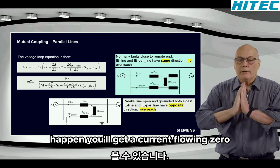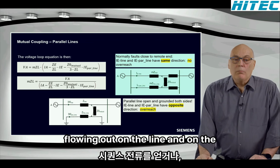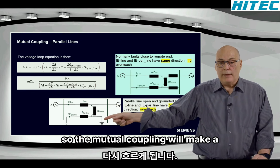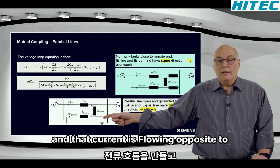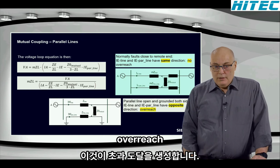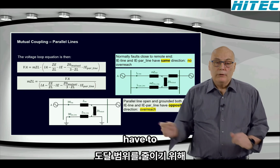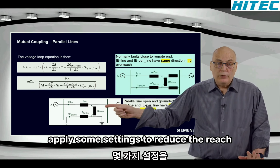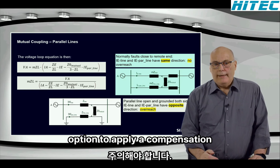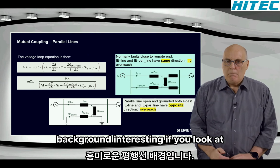You'll get a zero sequence current, or IE, flowing out on the line, and on the parallel line it will couple and flow back in the opposite direction. It is coupling, so the mutual coupling will make a circulating current flow here, and that current is flowing opposite to that one. And that would create an overreach. So during the parallel line open and grounded condition, one must be careful. One may have to apply some settings to reduce the reach, or, as we will show now, we have the option to apply a compensation. So this is the parallel line background.